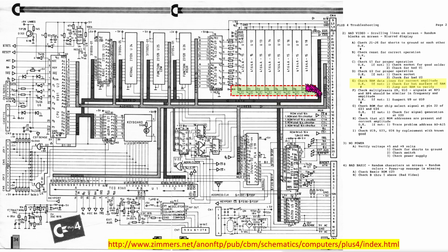And then you can use that to conclude that something is pulling the data bus low or high, and that the driver voltages and currents on something on the bus are not strong enough to pull it high or low. They also say that we should check the multiplexers, but the multiplexers actually affect the address lines. And if the addresses were the source of this error, we should think that every one of the memory bits should have the same fault, and that would not just affect one bit if this was the error.